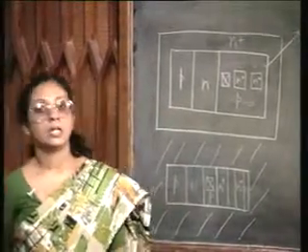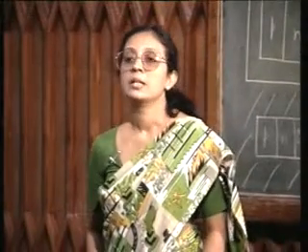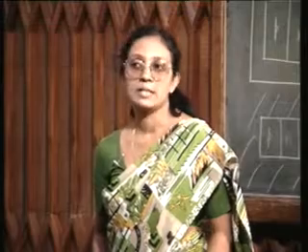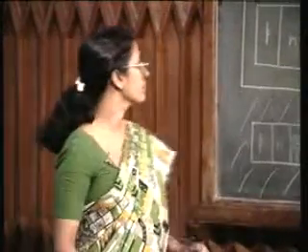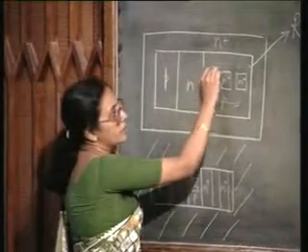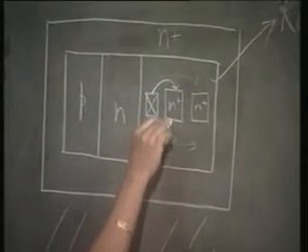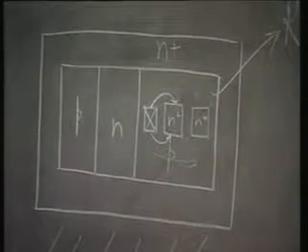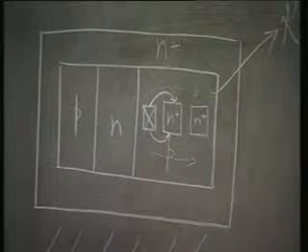But even though space saving is a great advantage, the oxide isolation case does have a small problem. And what is that small problem? Look at the way the current flows from the base to this. I have to have multiple collectors in the I square L. Multiple collectors means I have so many fan outs.